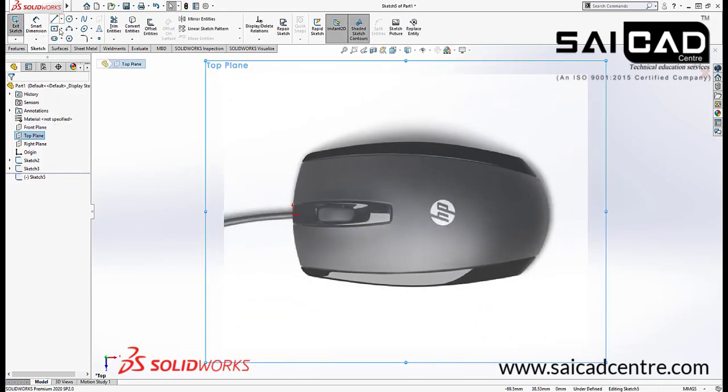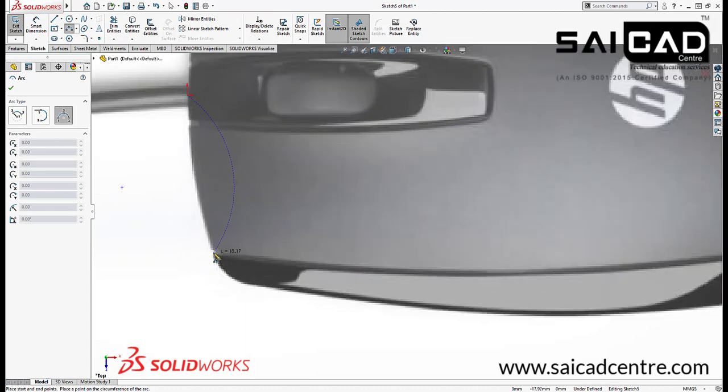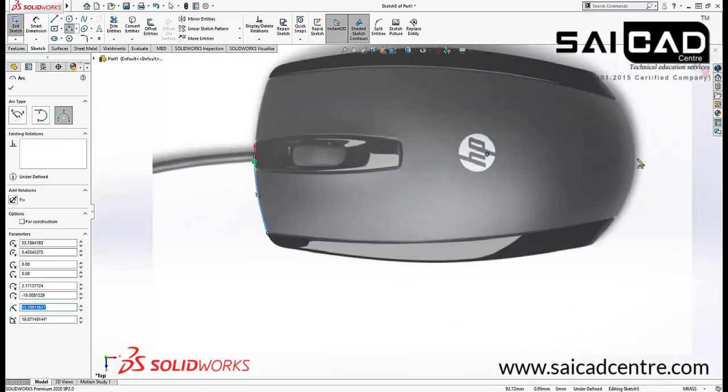And now I can just use the arcs. So don't create the full object, you can just create the half object, and the half will be mirrored. In surfacing, just half surfaces or half section is enough to create a full body if the object is symmetric only. So I can just use the arc right here like that, and again I can use the arc